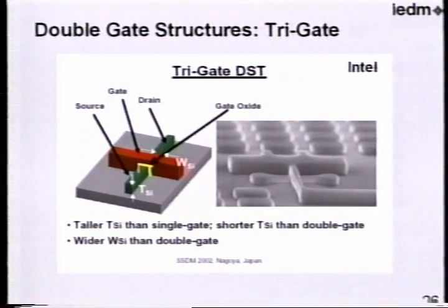Basically that's a thin body on top of SOI, but instead here you make a double gate device on top of that using the same depleted substrate architecture. So the nice thing about this device is it does relax some of these dimensions in terms of the fin itself. It's basically shorter, so it's not as tall, it's wider, and easier to fabricate.